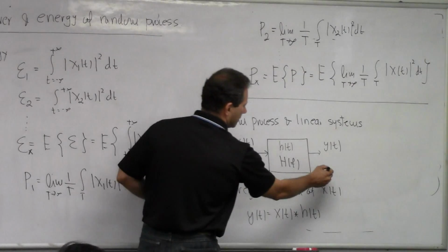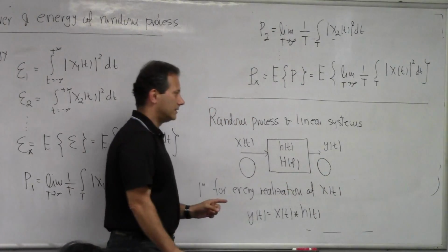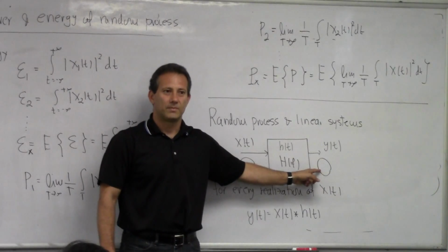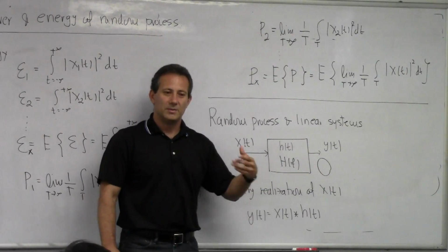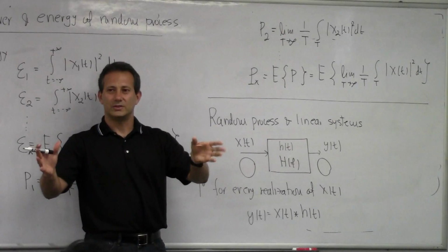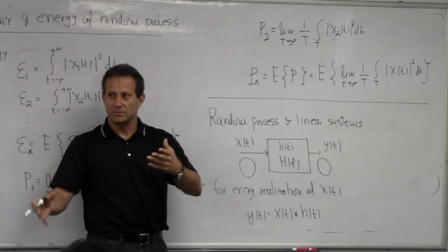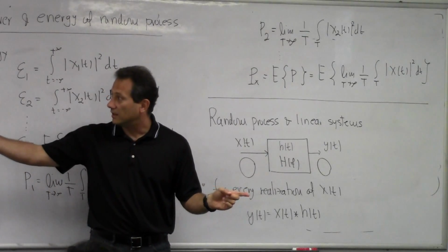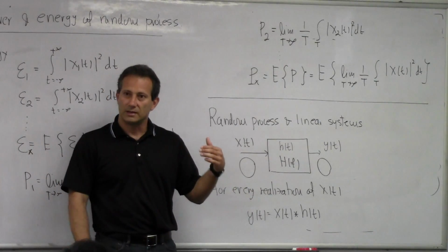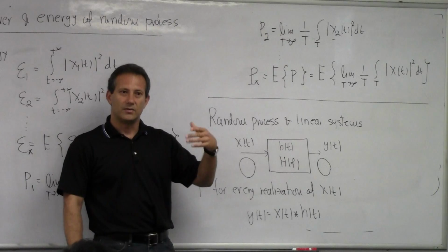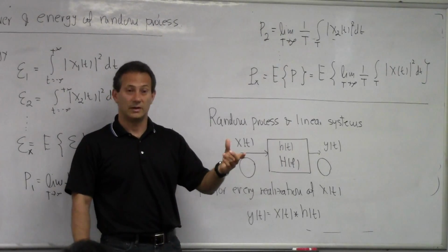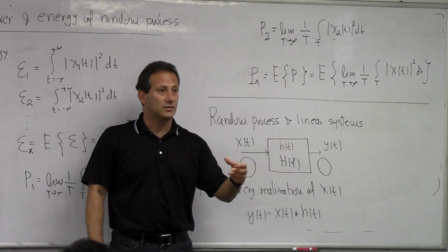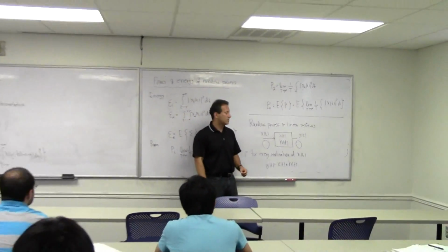And then I need a descriptor here that tells me how to characterize my output random process in the frequency domain. Let me just ask you now blindly, you haven't seen this before, so let me see what's your intuition. I've shown here, for example, that the autocorrelation function of the input and output are related through some sort of convolution, right? You see that the autocorrelation function of the output is the autocorrelation function of the input convolved with some impulse response.